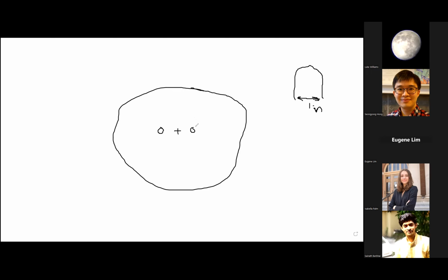Instead, what matters to us as a designer for this part is a lot more what the distance between these holes is. That way, we are able to control the tolerance for this 1 inch distance here.